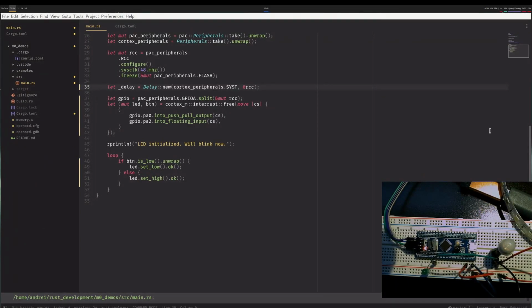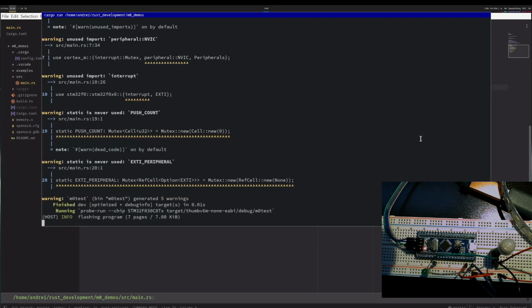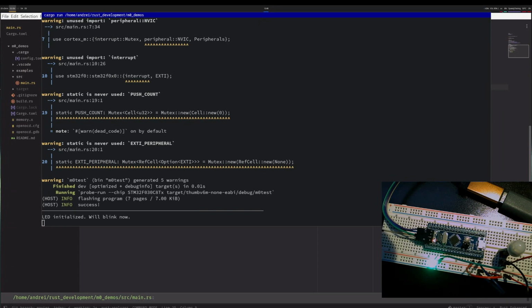I rearranged the connectivity a bit. I needed a shared ground for the LED and the sensor. So now let's run, and I expect the LED to turn on. And now if I sit very, very still, because these sensors are very sensitive, eventually it should turn off, and then it will turn on once I move. Let's try that. Notice how even the slightest movement actually turns the LED on, and then after a while it will turn off.